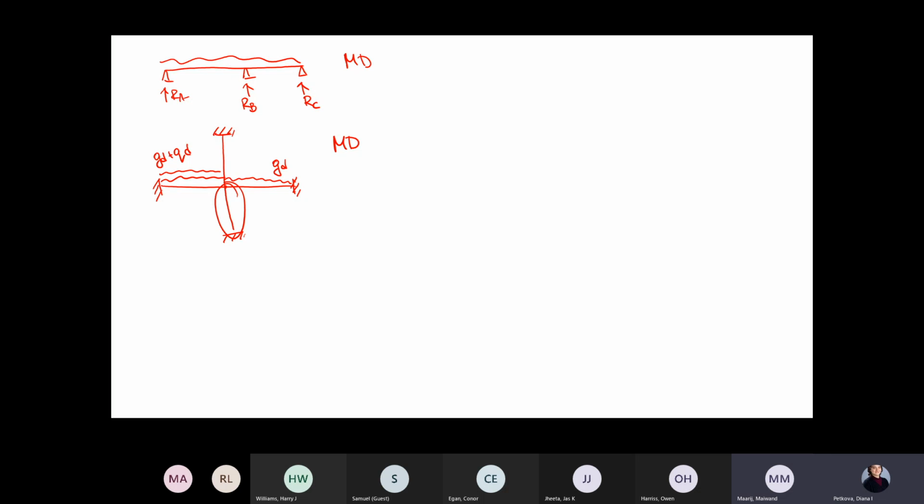The stiffness for the beams is halved. Yes, exactly, half. So 1/2 EI over L. This is because it is a more realistic representation of the contribution of the beams in this analysis.